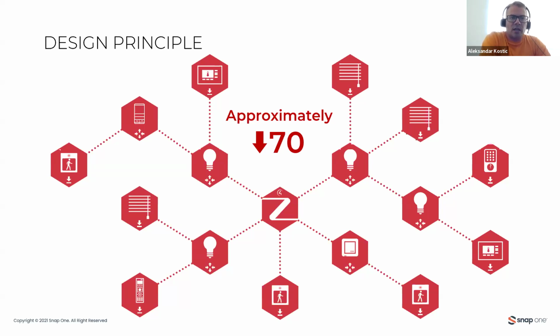So when you are designing maybe a bigger network, a bigger Zigbee network across a wider area, it is important that you take into consideration which Zigbee network belongs to which Control4 controller. It is the best practice that it is clearly obvious what devices should be attached to what Control4 controller and as Zigbee nodes.